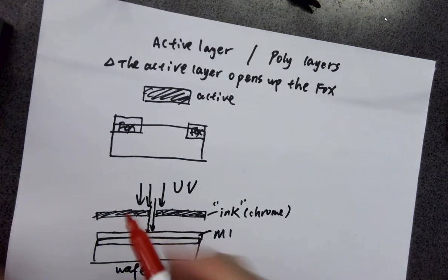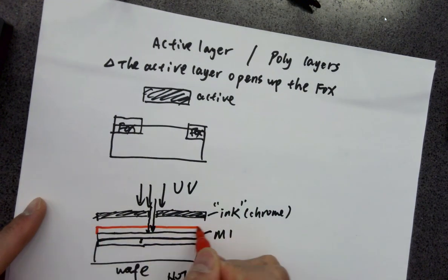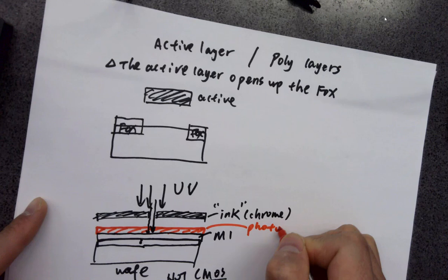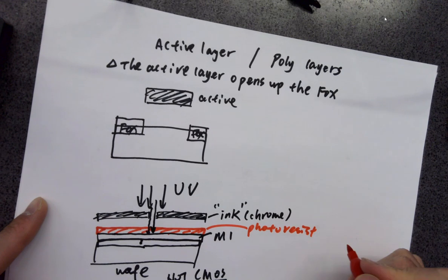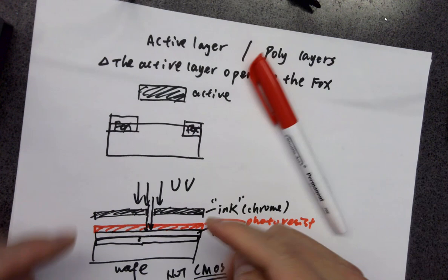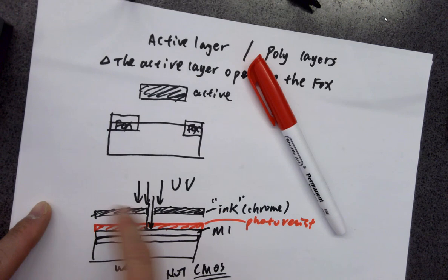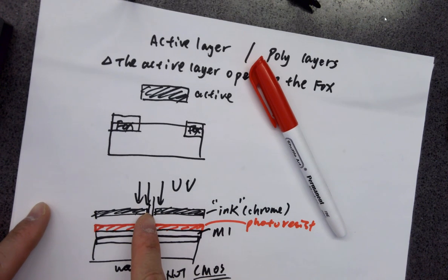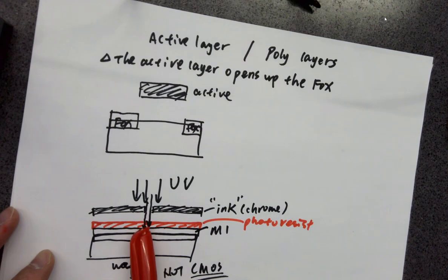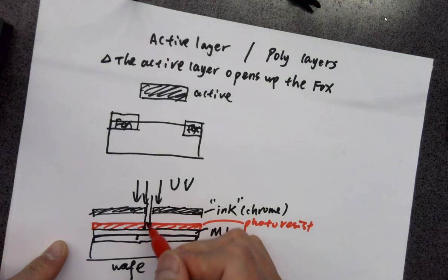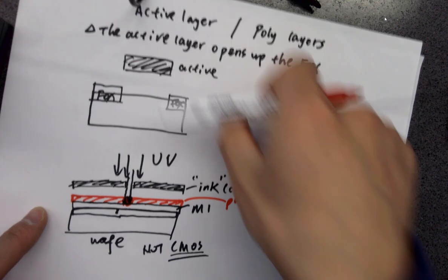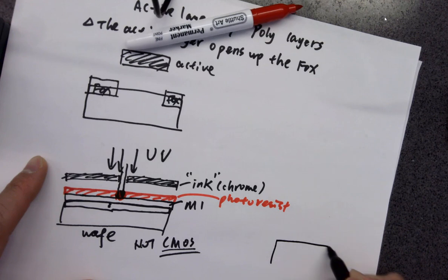But before that, I need a photoresist here as well. Okay, photoresist. Another layer. It's being coated. It's a photosensitive material. Okay, it's being coated on the top of the metal one, and you put a mask on the top. So this mask is your design. So this hole could be a wire, could be anything, or opening on the mask. So exposed under UV, the UV is going to cure this little area because it's able to get through and cure this area. So it's going to change the property of this area. If you remove the mask, you are getting something like this.